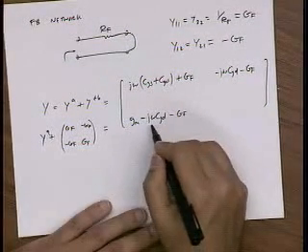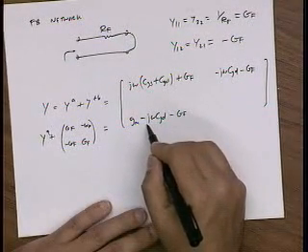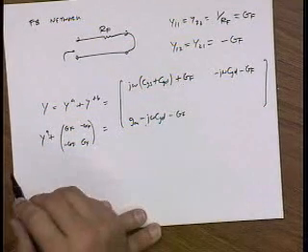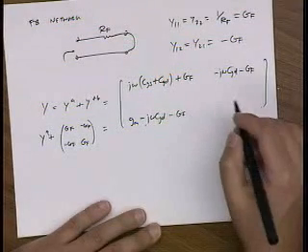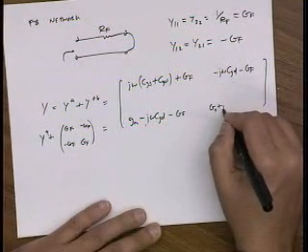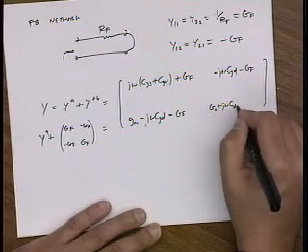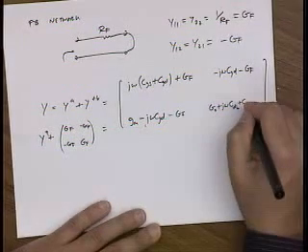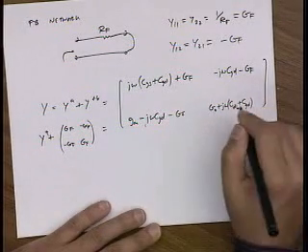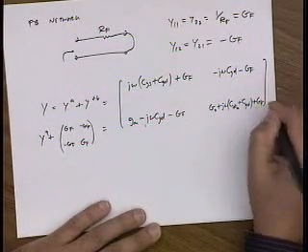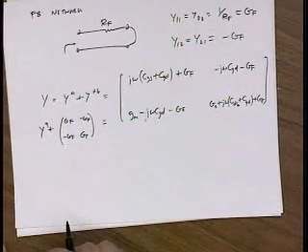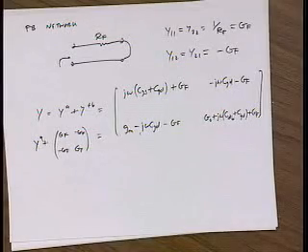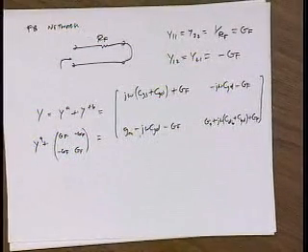So we can see now that the effect of the feedback is the total feedback, which is the resistance in parallel with this capacitance. And finally, the output admittance of the transistor is G0 plus j omega, let's say drain to bulk, plus Y mu, C gate to drain, plus GF. Okay. So now this is the total Y parameters of the amplifier plus the feedback network. Questions or comments?